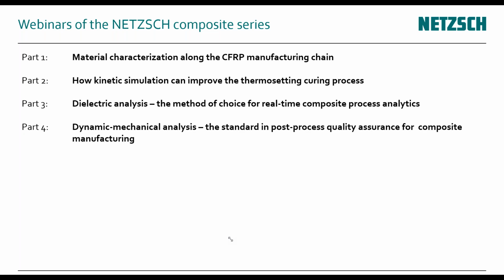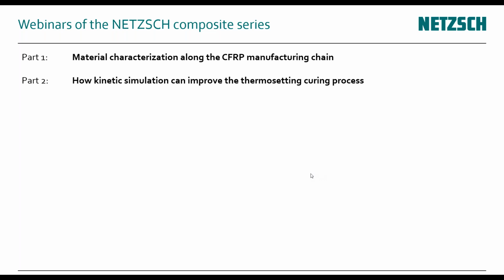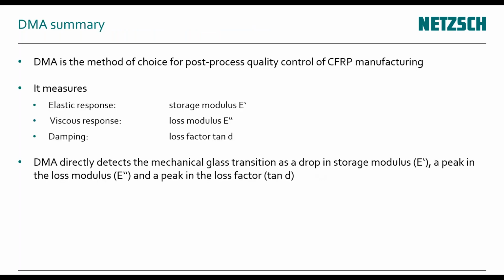Second question: which DMA type is best for FRP to determine Tg? Tensile, bending, shear, or another? That's a very good question because I did not go into this too much. A question that we received from Turkey. Well, I can still say good morning, Turkey. But I can answer this question. All measurements that you've seen here were done in bending.